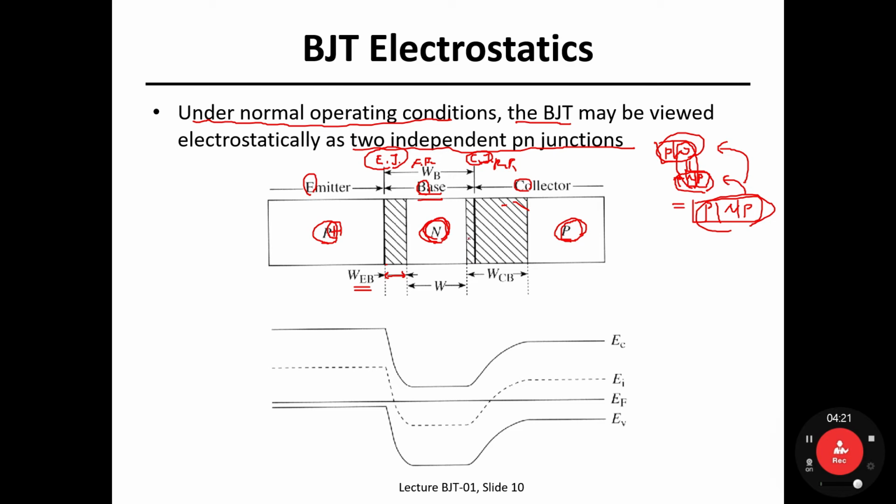But from the illustrated depletion layer, we can guess that the doping concentration in the N side is slightly higher than in the P side, because most of the depletion layer has formed in the P side, which is the lightly doped side.